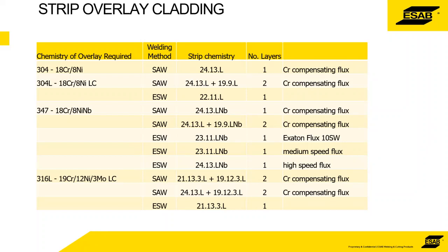Then we have another question which came in. Can 7mm high be achieved on one layer run? That was for you, Paolo. Yes, thank you. It is technically possible, but there is a high risk of slag inclusion on the overlaps, because the preferred thickness is usually around 5mm per layer or per run. When it's getting to 7, it's possible, but you need to pay much attention to the overlaps.